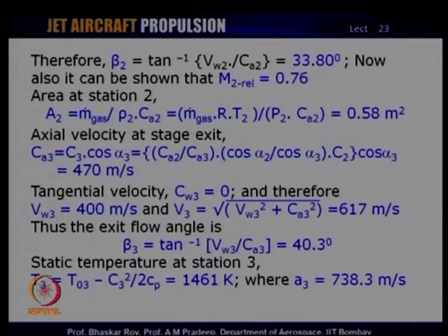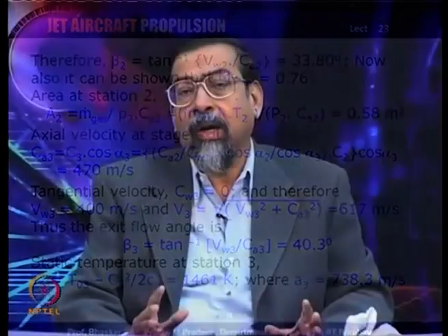And the other thing is, a higher level of work done is being accomplished by increasing the turbine entry temperature, and this increase of turbine entry temperature is quite often the focus of attention of modern research, with more cooling technologies applied. We have prescribed that this particular problem actually applies blade cooling, and that is how that high entry temperature was admitted.